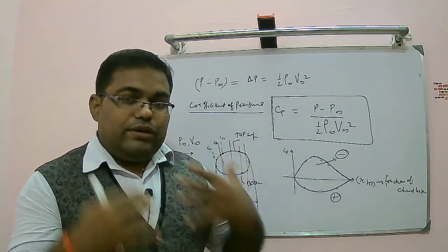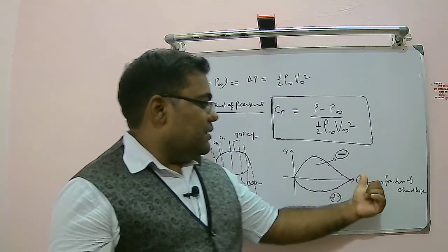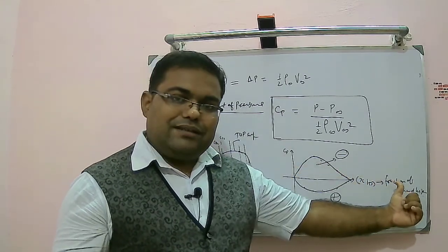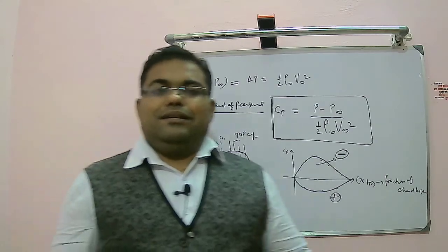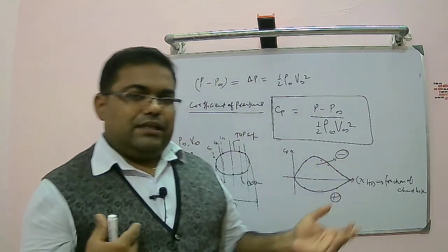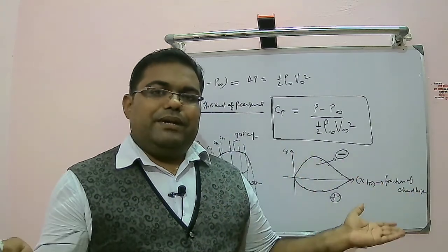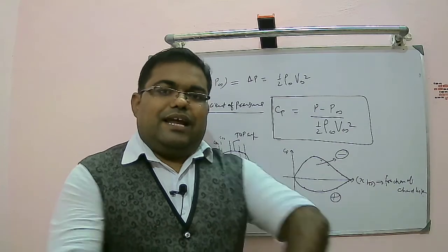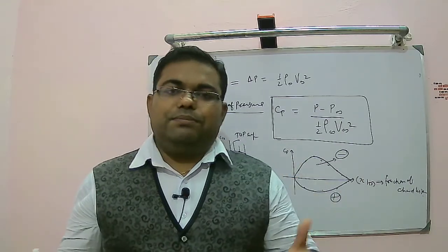When you are talking about drag, drag will be acting in the same direction of the flow. So if you take the pressure difference between the front and back of this pressure distribution, that will give the drag. The sideways force also can be calculated front and back, this side and that side. If you measure the pressure difference in a three-dimensional domain, that will give the side force. So the different aerodynamic forces, easily you can calculate if you know the pressure distribution.